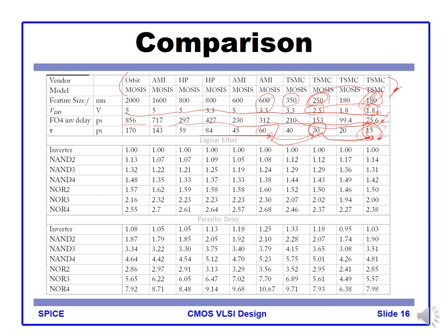Let's say for the logical effort for inverter, we specify that inverter logical effort is 1, and for different logic gates, we say that NAND 2 is always the second best, right? Second best, close to the inverter, right? Then logical effort, so NAND 2 is fast. For the parasitic delay as well, we see that NAND 2 is also fast compared to other logic blocks. So the inverter, we have a parasitic delay a little larger than 1.